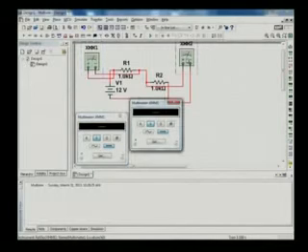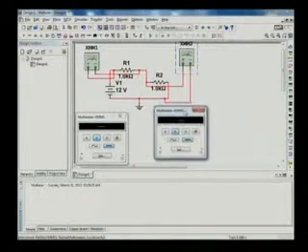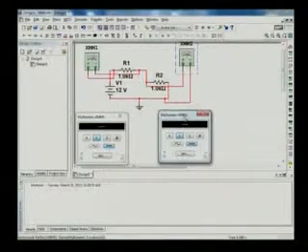Double click on multimeter 2, it is already in voltage, right? So if you solve it theoretically, the voltage across R1 will be R1 upon R1 plus R2 into 12 volts. So you will have 1 divided by 2 into 12, so you will get 6 volts.